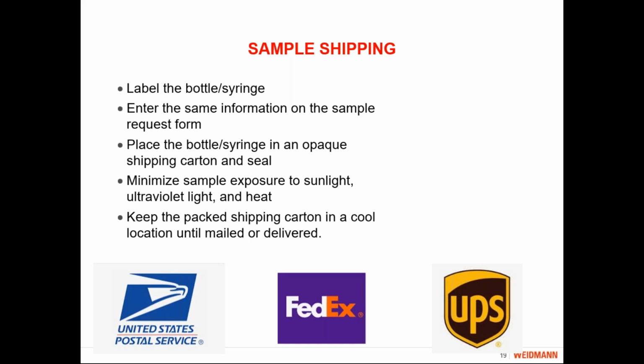We know that some places like wind farms or solar farms, where you may have a lot of transformers on a site, you may want your personnel to sample a bunch of transformers and then send them all in a batch. And you may not be able to do them all in a single day. Well, that's okay, but if it's going to take more than a week to get them all, then do it in separate batches. Take this first batch and send it in, and then when you get the second set done, send that in as a second batch. Try not to sit on them for 2 or 3 weeks until you can get a high volume of samples to send in all at once.